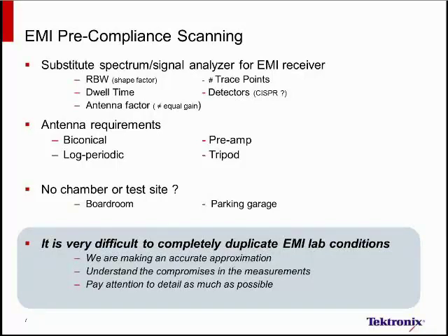On the physical setup itself, we'll also need the antennas to perform the experiments. Biconical antennas are very popular. We may be able to use a log periodic. We will need a tripod. And depending on the distance the antenna is from our signal analyzer, we might need a preamp in the situation as well.